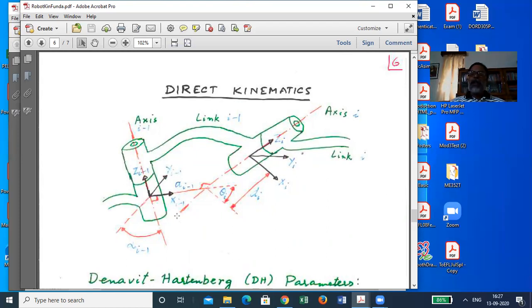typically revolute joints and prismatic joints, though in more complicated kinds of manipulators there are spherical joints also, and other kinds of joints possible. But mostly it is revolute joints and prismatic joints. In serial chain manipulators, with which most of this course will deal, it is mostly open chain, so revolute and prismatic. In an open chain manipulator, there is no way to have a spherical joint because spherical joint actuation is not in the technology.